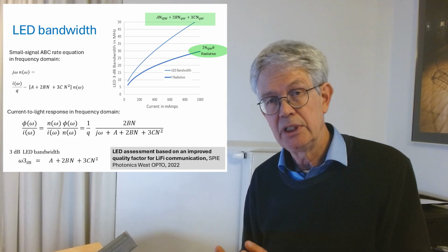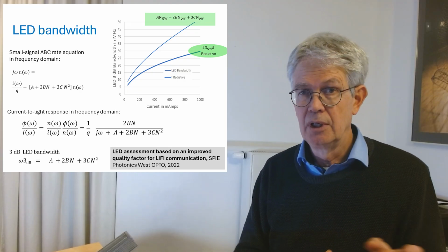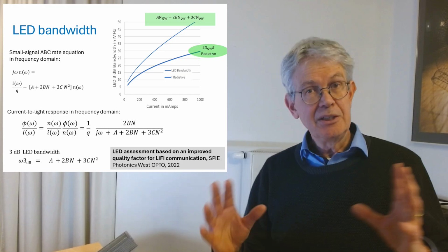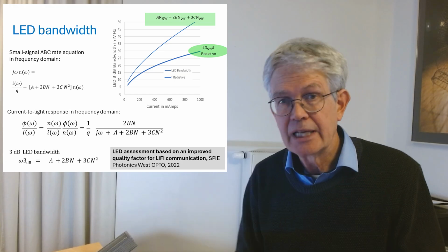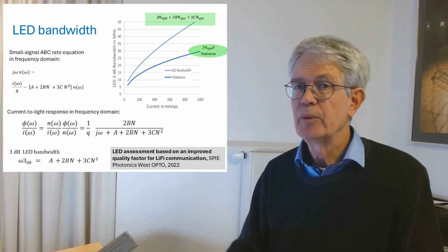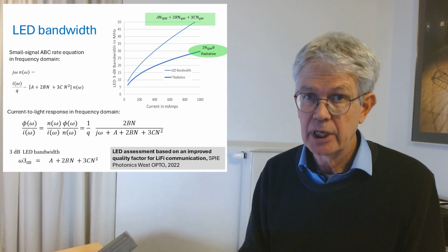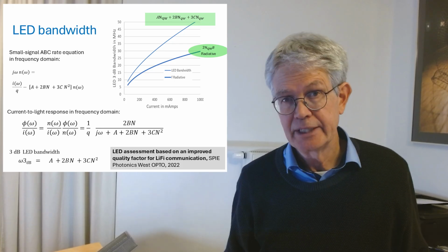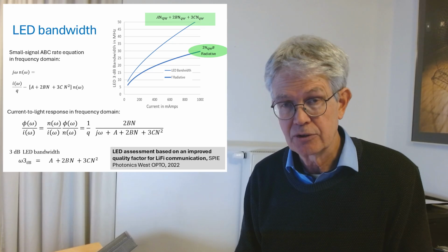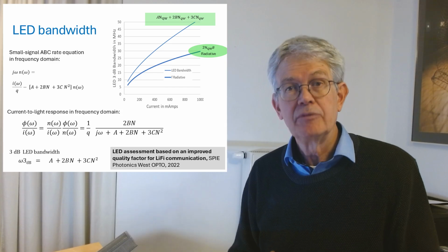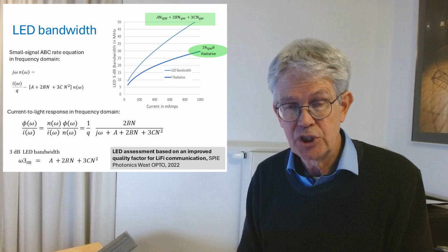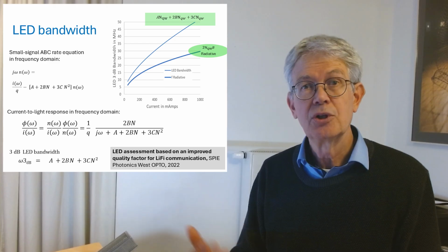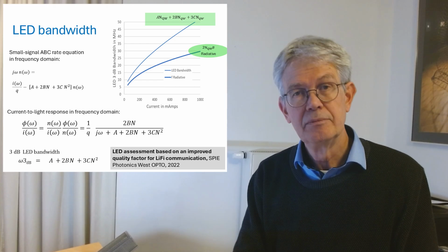We like micro LEDs, they have a higher bandwidth. But their efficiency goes down. So it's an interesting debate about where to find that optimum. And that's not always by going for higher and higher current densities. At some point in time, you may just also like to benefit from a stronger signal-to-noise ratio. Have a system that is highly efficient, that generates a lot of photons, a lot of modulated photons for the current that you feed in.